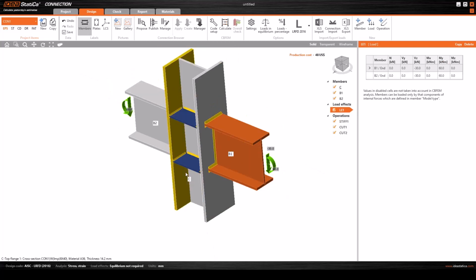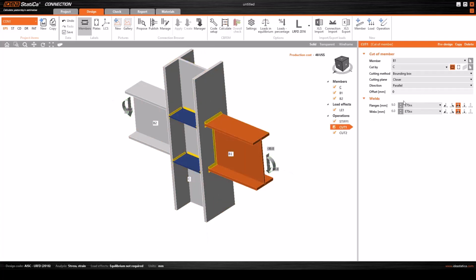Now for simplicity, we don't have any pre-designed steel beam columns, so we are just considering designing the connection. We want it to accept this loading with this template beam column. We want to check with this sort of configuration, let's see, 9mm flange and web is 6mm using E13, whether it will pass this loading or not. In case it doesn't pass, we will have a lot of options to improve this connection and finally get a verified connection design.